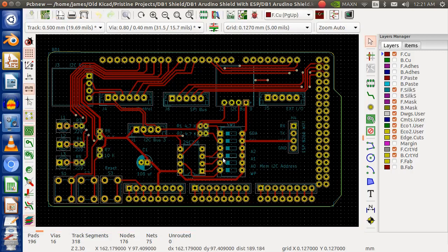Now in the printed circuit board editor, you can see again the similar layout. This is the dip switch. This is the footprint for the dip switch. Notice that it's different from the schematic symbol. This has to be exactly the same as an actual dip switch, a dual inline package switch that would be soldered into the board. This is the footprint for that memory chip, which is an 8-pin dip. And remember, number 1 was down here, so it's facing to the bottom of the board.